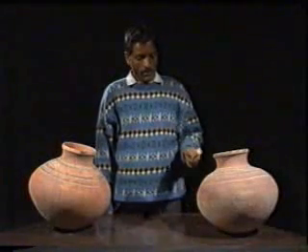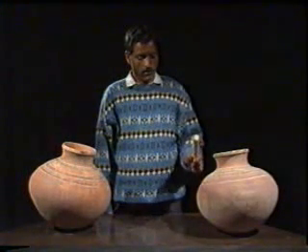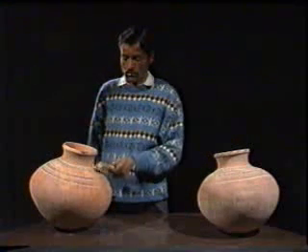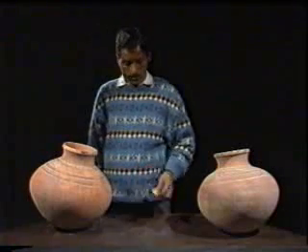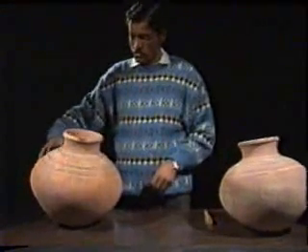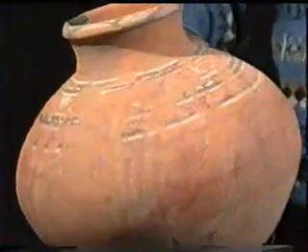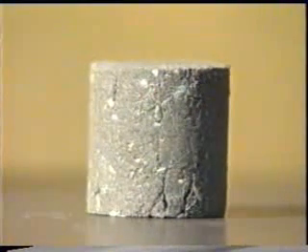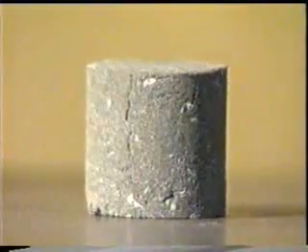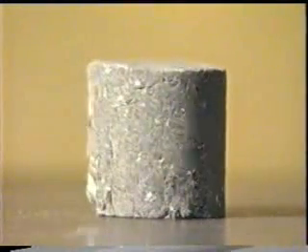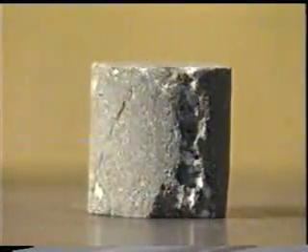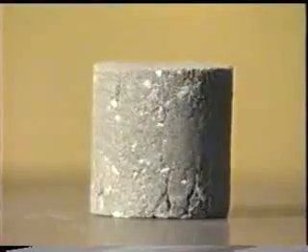The concept of soundness can be explained with the help of two similar earthen pitchers. On striking the first, we get a continuous ringing sound, whereas in the second pitcher, the sound is dull, indicating discontinuity in the movement of sound waves, which is due to the existence of cracks in the body of the pitcher. In cement, cracks are developed due to the presence of free lime and magnesia, which slakes slowly in the presence of water and increases manifold in volume.